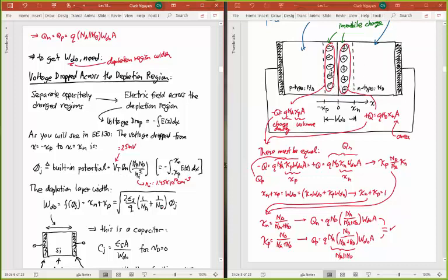And we will return to this concept of potential later on. But right now, because it is the potential that stops the electrons and holes from moving, that equilibrium potential determines the depletion region thickness, or depletion region width, right? And so it should not be surprising that for that depletion region width, if I write out the equation for